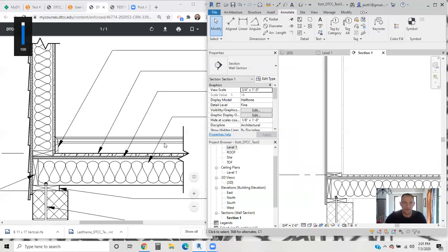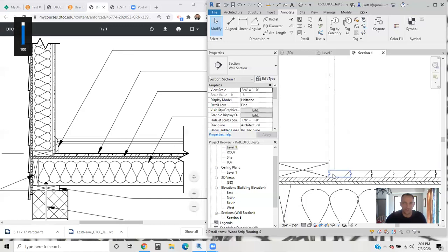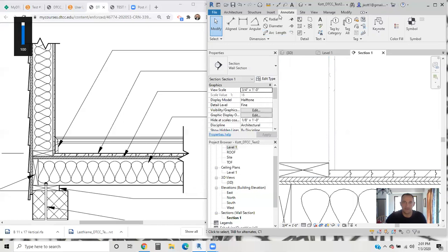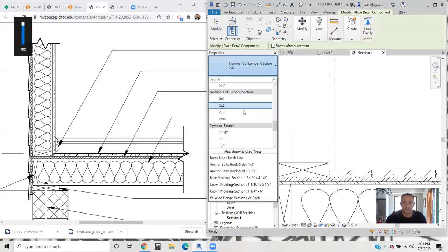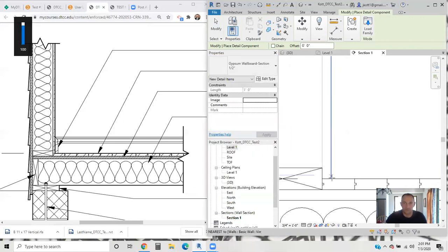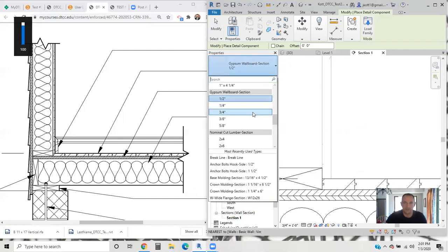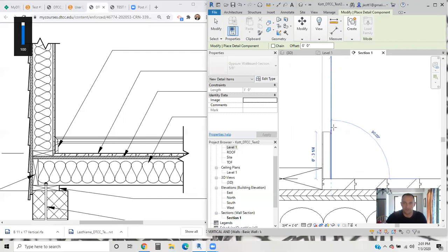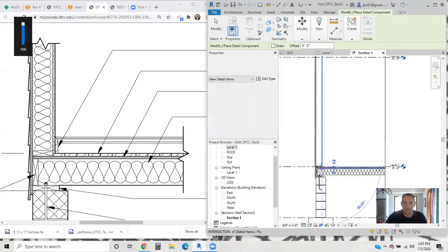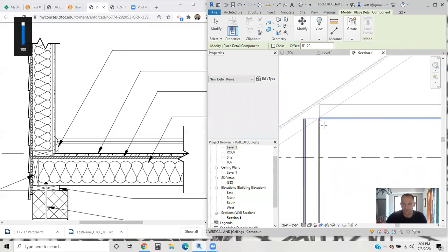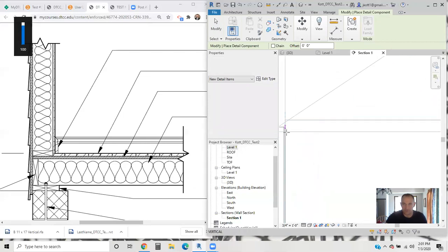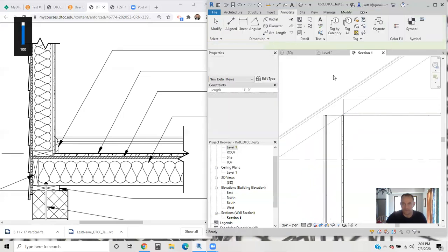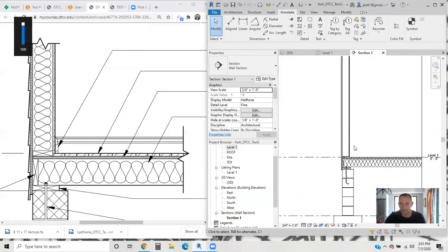And then we'll do the drywall, which is just inside of that, and it's another family. So come in here, click the gypsum drywall. I'm thinking this is 1/2-inch drywall. Oh, no, it's thicker than 1/2 inch. It's 5/8 inch drywall. Interior drywall, typically 5/8 inch. And that's coming all the way up the wall. So just like the plywood, we'll snap it here to the top of the wall. You can see that it's kind of like that wall assembly is being built out.